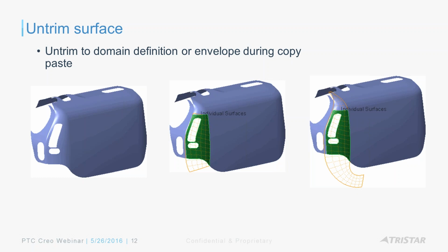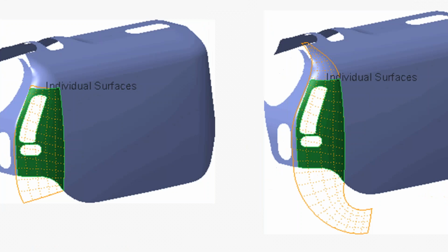When you do a copy-paste of a surface patch, you can see how it's essentially extrapolating that to its original domain, as you can see here, right? So right in here as well as here, right? So that's something that I may want to use when I import geometry, maybe for repair purposes, right? I don't have the original geometry that they used in their CAD software, but they gave me the final quilt, but during translation I've lost some data, and now I'd like to extrapolate from there.